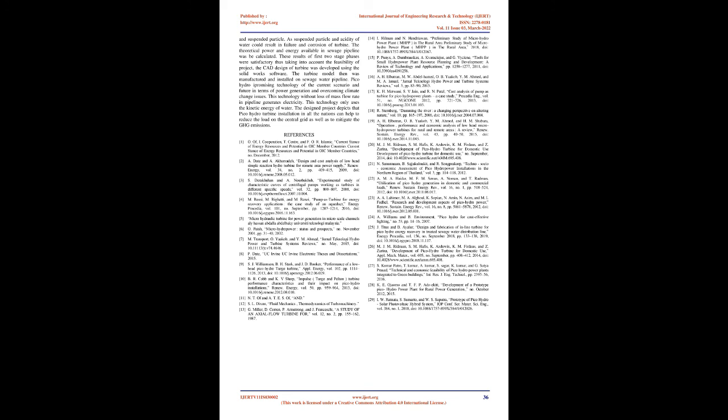To get the maximum out of Picohydro projects, site visits and surveys must be conducted to take into account the head and flow rate so that the expected power outcome may be calculated. These surveys will help to make Picohydro projects more economical. Continuous inspection of Picohydro must be conducted and maintenance like greasing/lubrication of bearings must be brought into business to enhance the lifetime of the project and reduce the power losses as well. There are many key points that ensure the bright future of Picohydro. Few of them include high grid cost in remote areas, low head sites being ideal for Picohydro, improved living standard of remote area communities, and green energy conversion technology etc.